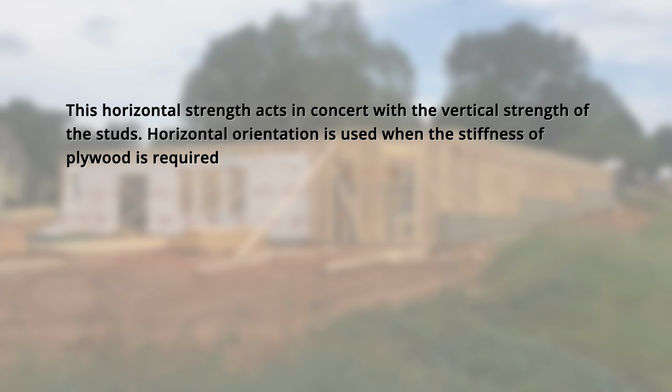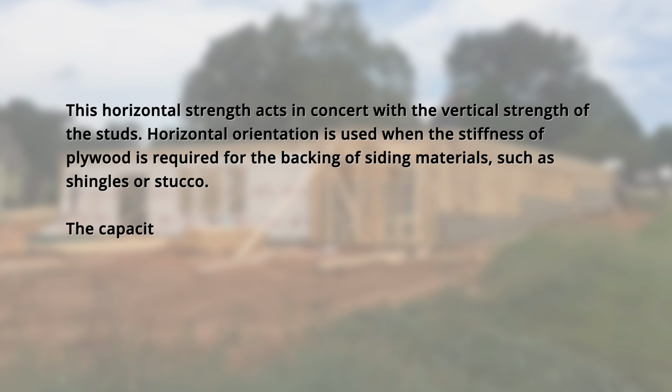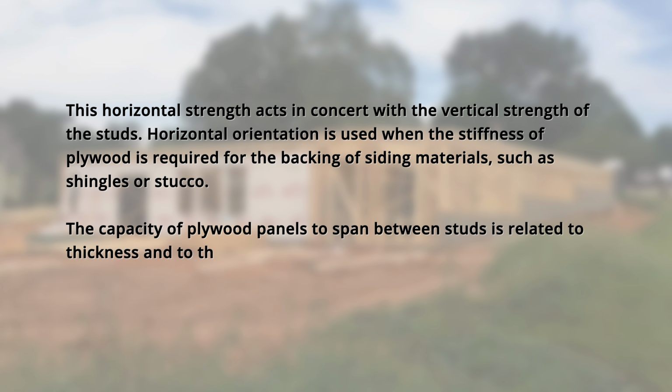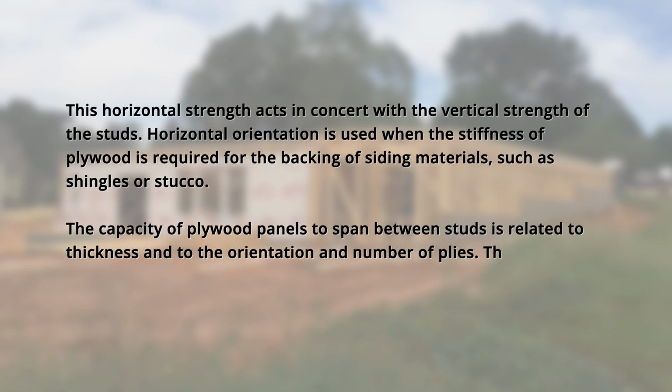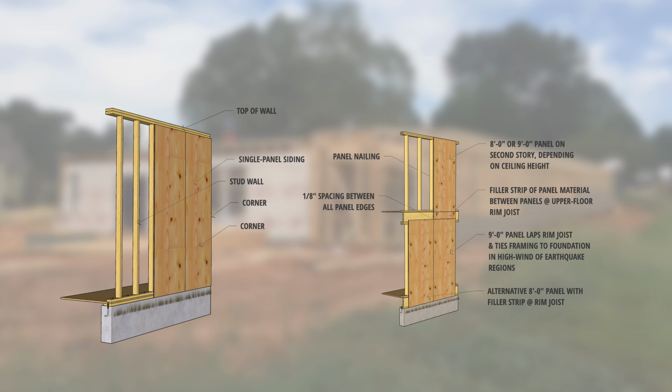Sheathing. This horizontal strength acts in concert with the vertical strength of the studs. Horizontal orientation is used when the stiffness of plywood is required by the backing of siding materials, such as shingles or stucco. The capacity of plywood panels to span between studs is related to the thickness and to the orientation and number of plies. The spanning capacity of composite sheathing. Let's reference this detailed illustration down below.